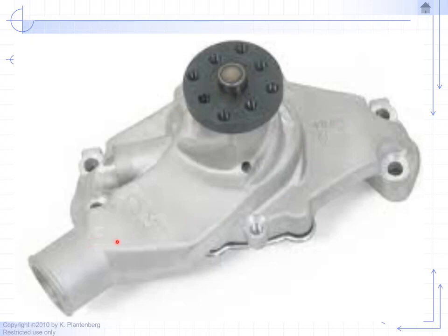And once you come up with a rough shape from the mold, then you can go ahead and do some machining. You can machine the hole, for example, here where the water hose attaches. You can machine the bottom where you have this foot, and you have another foot here. You machine it so these two surfaces are parallel and coplanar, and then you can mount to the front of the engine block. And you want a nice seal. You don't want anything to leak as far as water coolant.